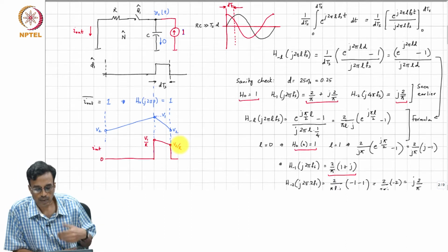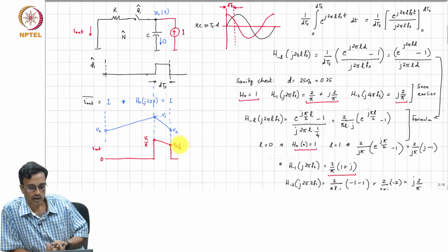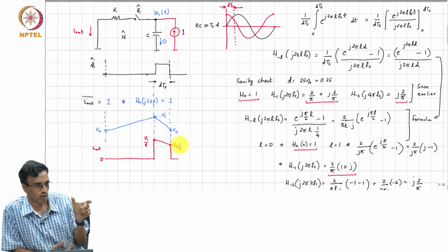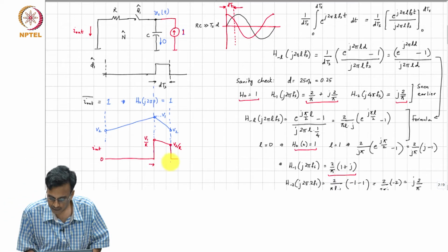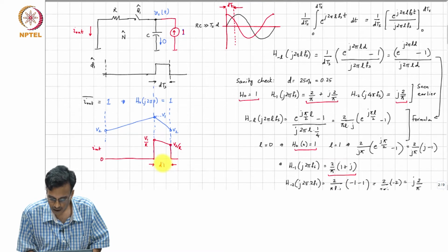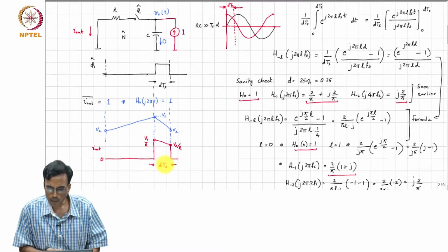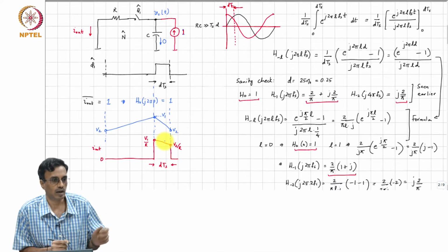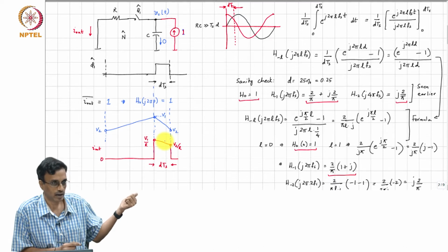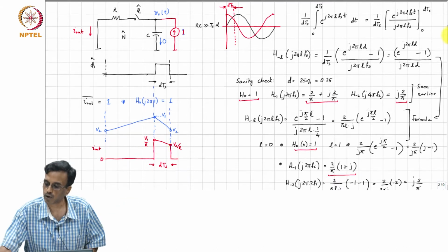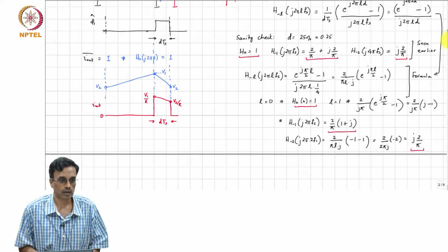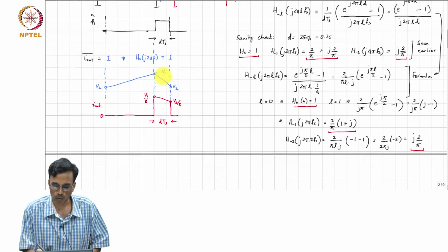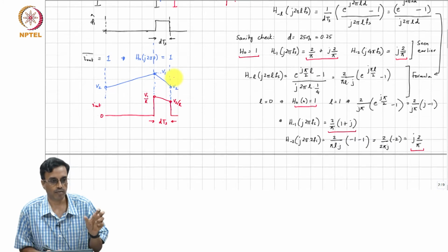Yeah. So, basically if the capacitance becomes larger and larger, the voltages V1 and V2 will come closer and closer to each other. Okay. And this is D times Ts, right. So, what comment can you make about the average current? We know that the average current flowing through the output is actually 1. So, what comment can we make about the average value of V1 and V2?